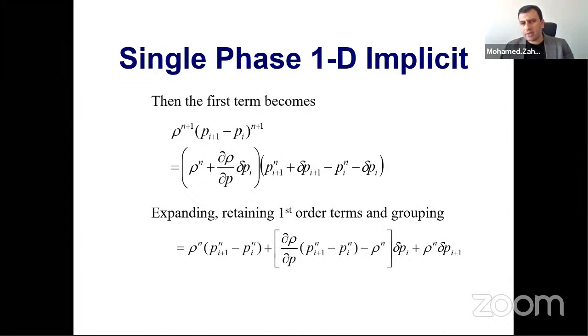Even in dynamic, what's the difference between dynamic and static for calculating the volume? Let's remind ourselves of the volume equation, because you calculate volume from material balance, mass in, mass out, change in the volume. If you have the change in the volume, mass in and mass out, you can calculate the volume inside already.